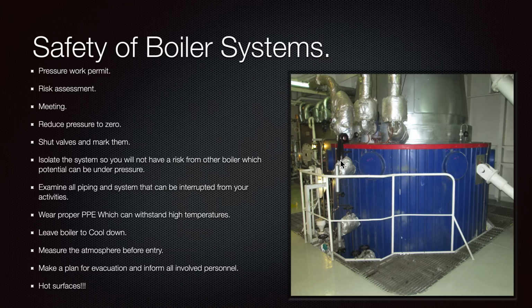So there is another means for identifying. And what is that one? It's our drain. So what we are doing, we see the gauge, we open the drain, we leave the drain open, and we drain all that pressure. But if we open the drain, how are we able to know that everything is drained and our drain is not clogged or plugged or something else? We will see it from here, from the drainage funnel.